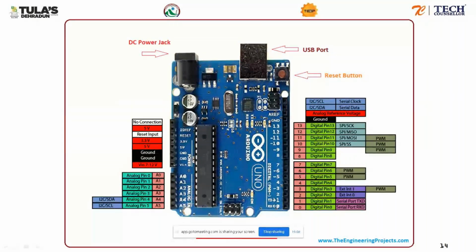These are 6 pins. First of all, always remember that when we are doing coding, whenever we talk about computer science, numbering starts from 0 and not 1. So the first pin is always 0, and the 10th pin will have a number 9 to it, because 0, 1, 2, 3, 4, 5, 6, 7, 8, 9. So 9 will actually represent the 10th pin. That's how it works in computers. So coming back to analog inputs, these 6 pins are reserved for analog inputs. This is analog pin 0, analog pin 1, 2, 3, 4, 5, and their names are A0 to A5.